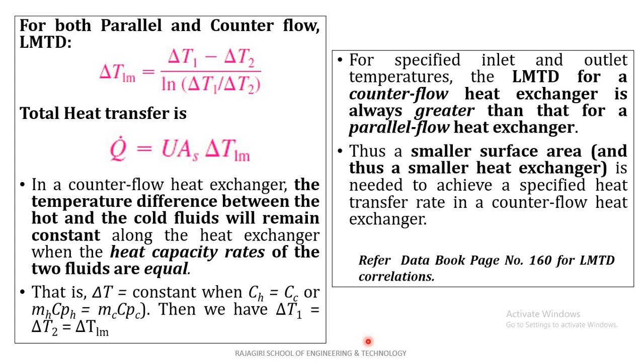Okay, so the total heat transfer rate is U As delta T LM, where As is the total heat transfer surface area, multiplied with the LMTD delta T LM.